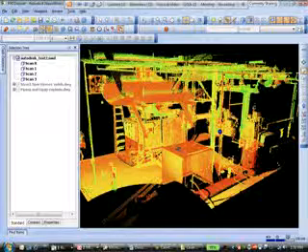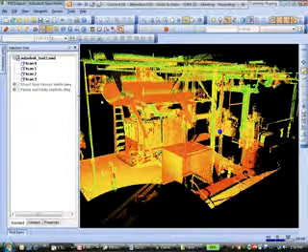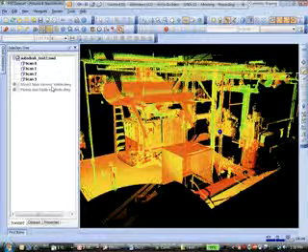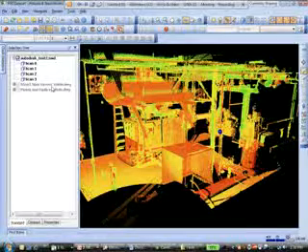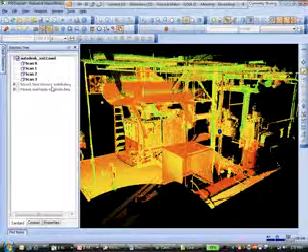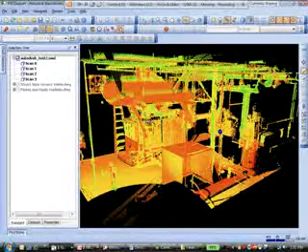That could potentially cause an issue if you were to be introducing some new equipment, and in the CAD file it looked like you had the clearance, but when you get on site you realize these components are going to be bumping into each other because the existing equipment in this room has sagged over the course of the years, or because it wasn't installed properly. So you're leveraging your point cloud, the scan data gives you a true as-built of what's in there. Not to say that the CAD file is wrong, but it gives you an extra realism. It gives you that extra bit of accuracy that maybe a CAD file will overlook.